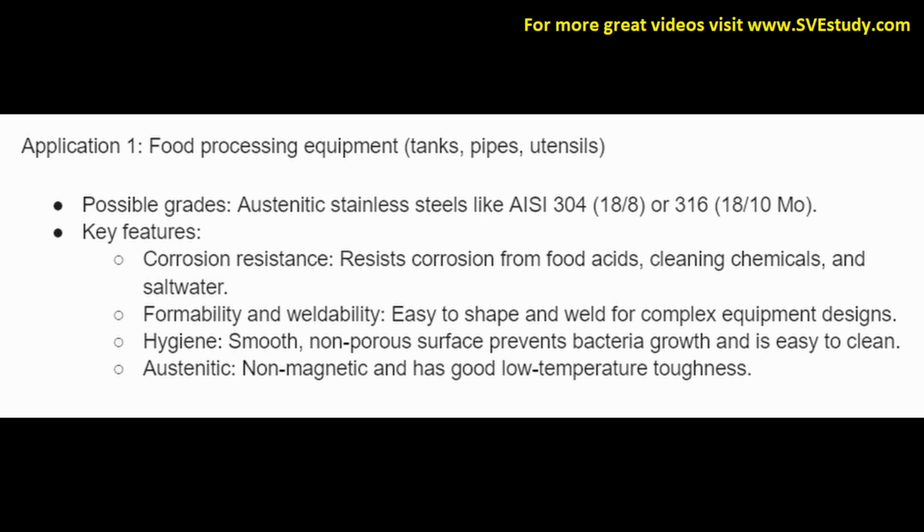Key features. Corrosion resistance. Resists corrosion from food acids, cleaning chemicals, and salt water. Formability and weldability. Easy to shape and weld for complex equipment designs. Hygiene. Smooth, non-porous surface prevents bacteria growth and is easier to clean. Austenitic. Non-magnetic and has good low temperature toughness.